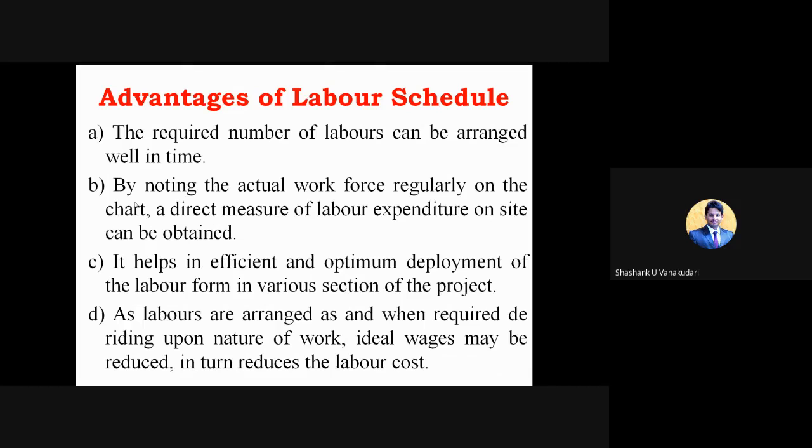And by noting the actual workforce regularly on the chart, a direct measure of labor expenditure on site can be obtained. So once you prepare this particular labor schedule, you will come to know how much money you need to invest, or need to get sanctioned from the top management just to pay for the labor wages. So even to calculate the total expenditure on the labors we require this labor schedule.